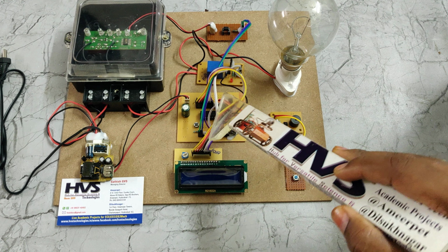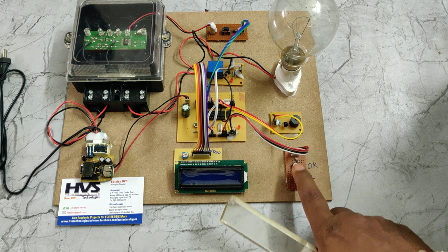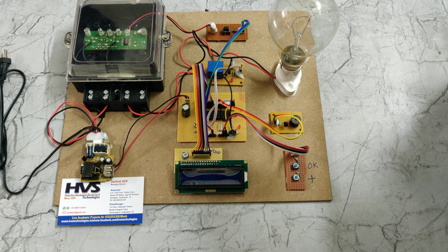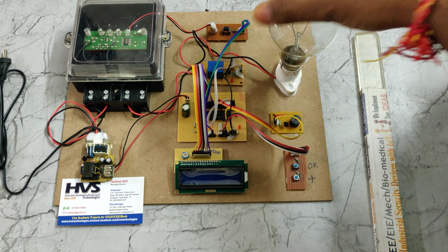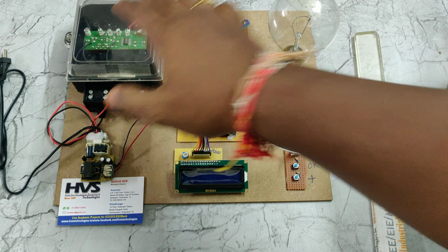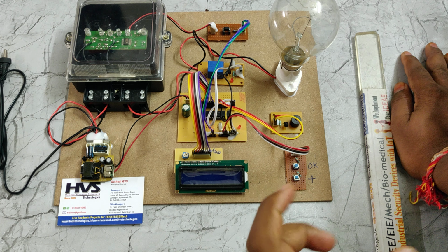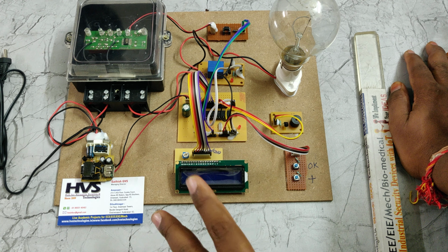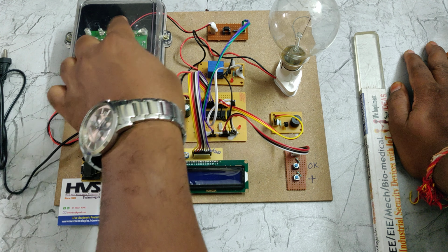When our microcontroller gets the 5 volts DC input, it starts reading input from the switches initially. Once we set that, it will read the input from this optocoupler IC. We calculate based on the LED pulses: when we connect a load, this LED blinks. Based on the load, its blinking rate increases. Whenever the time duration between two blinks is 1200 milliseconds, that will be considered as 1000 watts. That is the rating of our energy meter, meaning the current transformer present inside this energy meter.